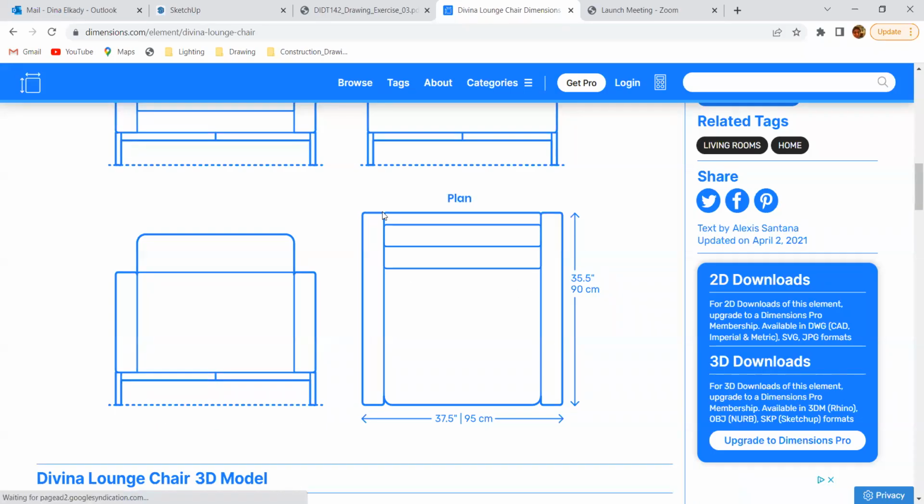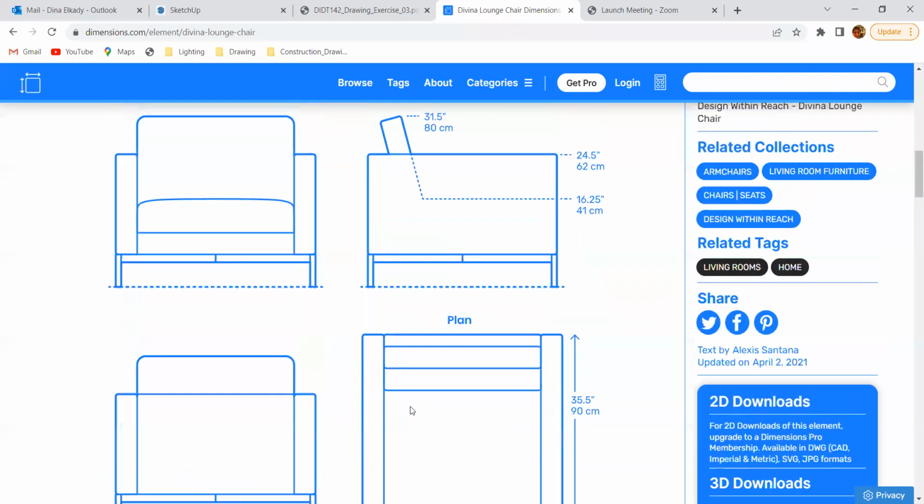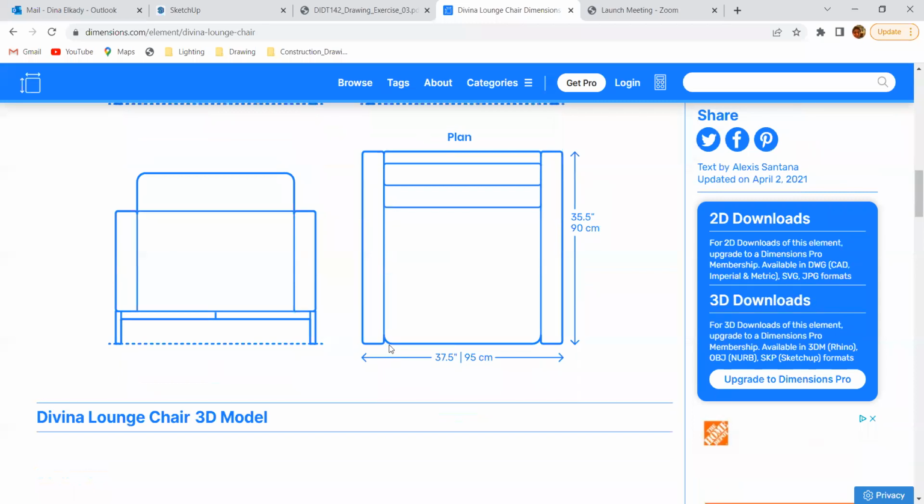We just have a lot of fillet edges to do. And this is going to take some time, because you can see that we do have some values that are bigger than others, especially at the seating area. So I'm going to start with the smaller ones, those seams, as you know, I used 10 millimeters for those, but then we might go bigger on the end of the seating. So I'm going to start with the arm, and then we're going to proceed from there.